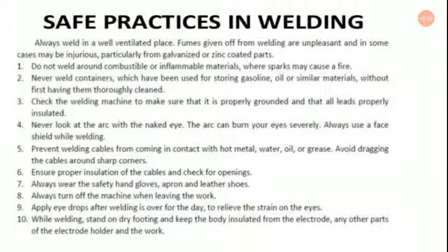Do not weld around combustible or inflammable materials where sparks may cause a fire. Never weld containers which have been used for storing gasoline, oil, or similar materials without first having them thoroughly cleaned.